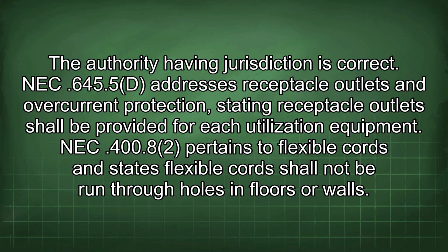The authority having jurisdiction is correct. NEC 645.5d addresses receptacle outlets and overcurrent protection, stating receptacle outlets shall be provided for each utilization equipment. NEC 400.8 pertains to flexible cords and states flexible cords shall not be run through holes in floors or walls.